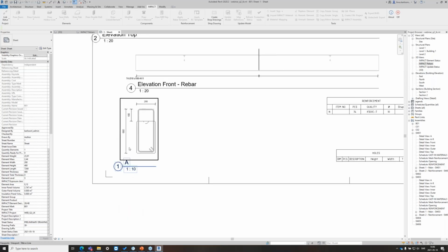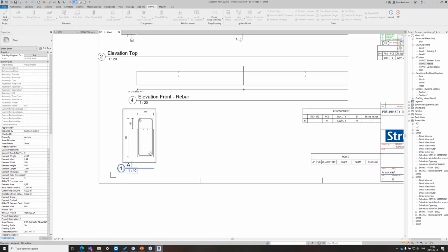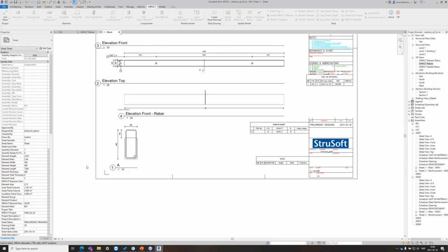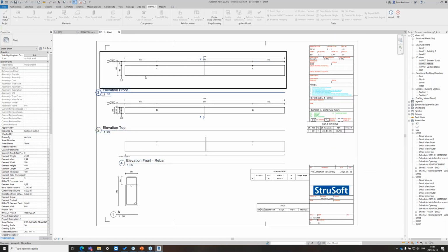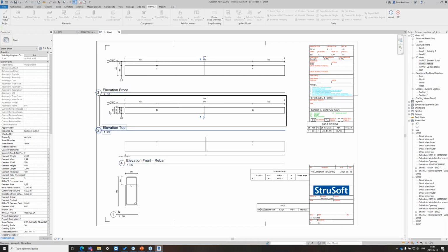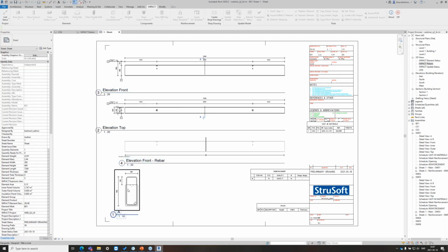And this of course can be used in other elements as well, but I think that it could be very common on a beam like this. So that's one new feature as well. Otherwise we have the same here, the scale to fit. Every view here is scale to fit, which means that we have the same scale. This one here has a fixed scale, so it's not corresponding, but if I put scale to fit here as well, I will get the 1 to 20.